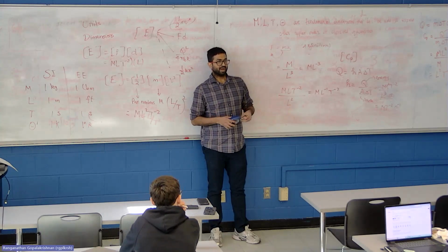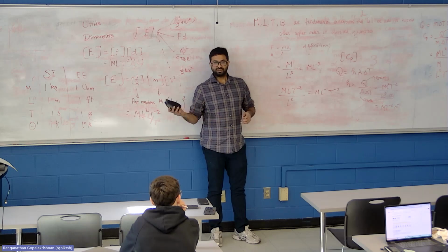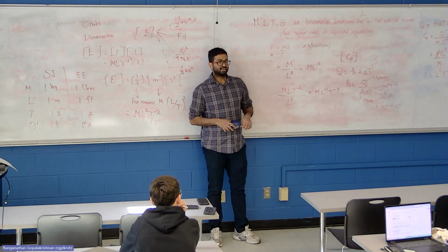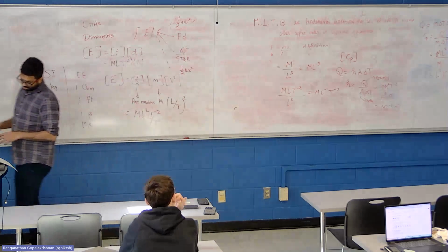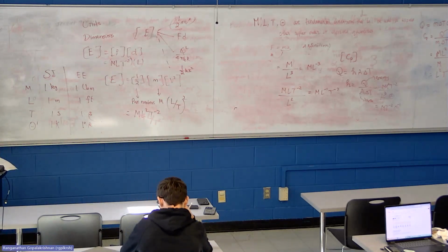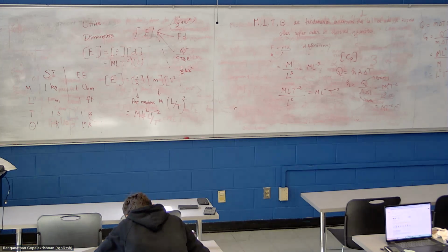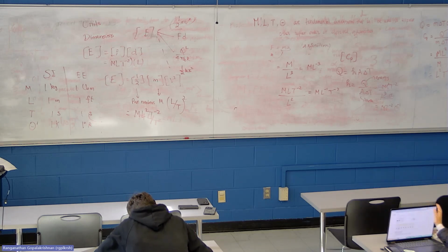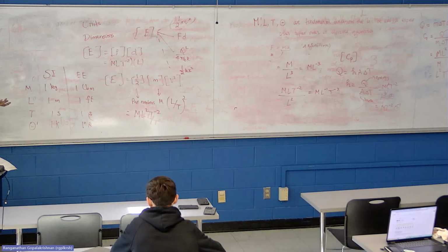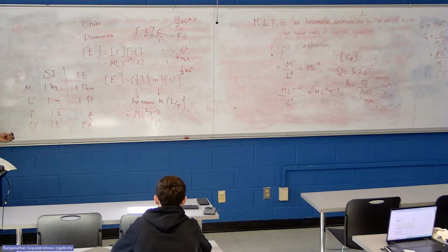It's okay to guess. I honestly don't know what you'll have. I have to look at the numbers. Yes, I'll see it float. Okay. So if you look at table 1.5, if you have your book in front of you, I said SAE 40, they have SAE 30. SAE 30 has a density of 912, and you know water has a density of 999. So it is going to sink, but just about, because the densities are almost the same. But you get the point that it's a liquid whose density is comparable to water.